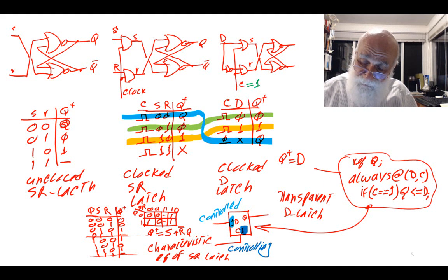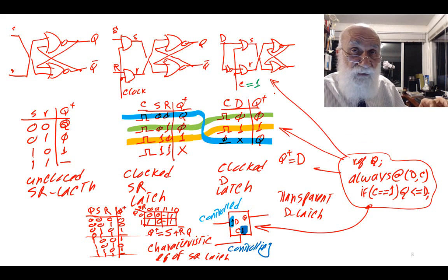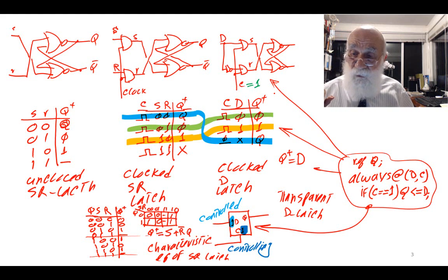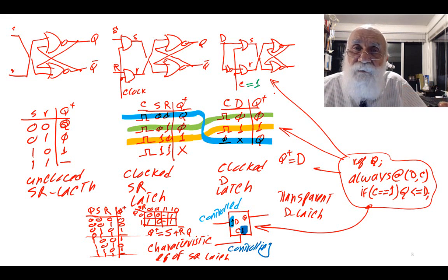Of course, you could write down the gate descriptions using assign statements and wire them like what you are seeing there, and that would still work the same way. But for memory elements, we usually use always statements because it's very descriptive of how they behave.